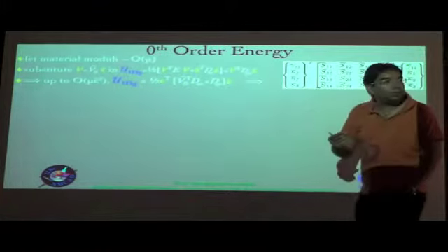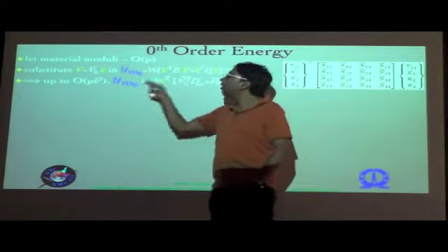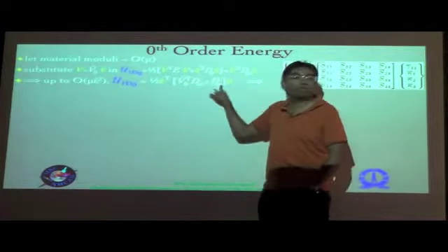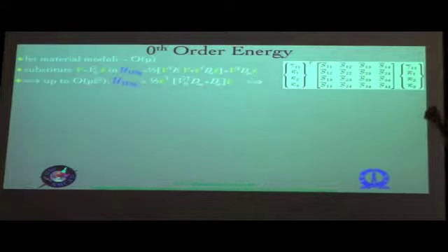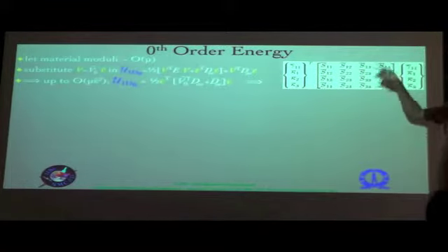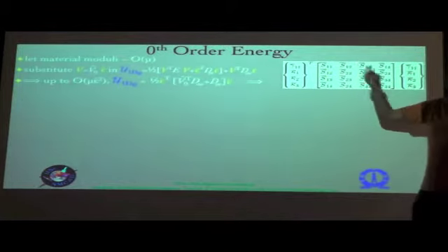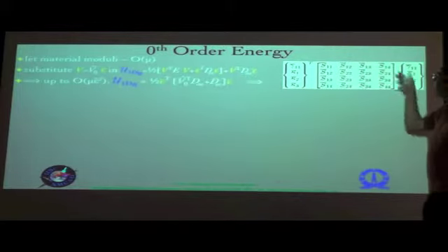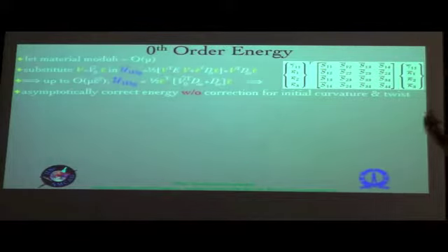Your warping is linear in the epsilon bar, the strain is linear in epsilon bar, and because the strain energy is quadratic in epsilon bar, you see epsilon bar on both sides, and this matrix between the square brackets becomes your so-called stiffness matrix, the 1D stiffness matrix at this 0th order approximation. In general it turns out to be a fully populated matrix, involving all kinds of coupling between extension, twist, bending, between the 2 directions of bending, etc., all contained within this S bar, but of course obtained numerically using the finite elements.